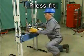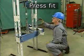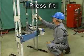A press fit is much tighter. More effort is needed to press the ring into place. A press fit is also called an interference fit or a shrink fit. Generally, rolling contact bearings have a press fit on the ring that rotates and a push fit on the ring that doesn't rotate. In most bearings, the inner ring is the ring that rotates. So let's take a look at some methods for mounting bearings whose inner ring rotates.